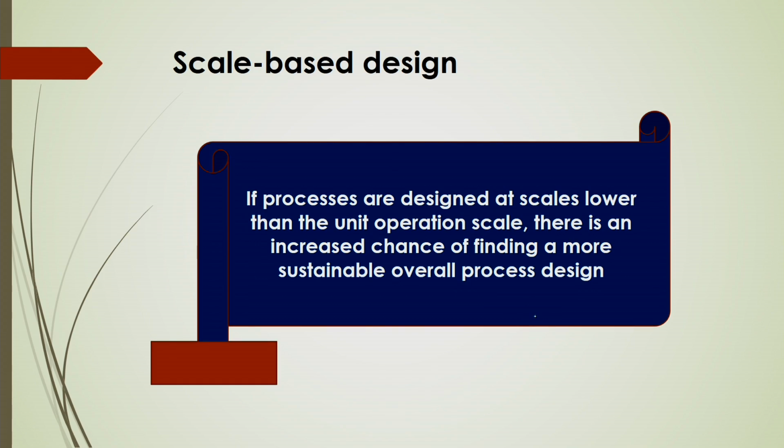So for that particular unit operation, at that particular scale, the unit operation should be intensified. That means for chemical processes like fast reactions, in channel-based systems you can get more interfacial area. So the scale should be reduced, like I told you, micro bubbles or nano bubbles can be produced to get more interfacial area.